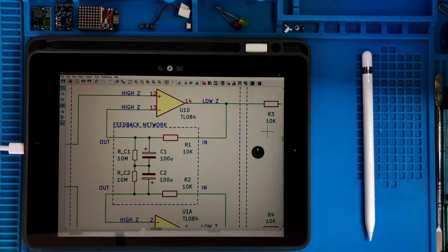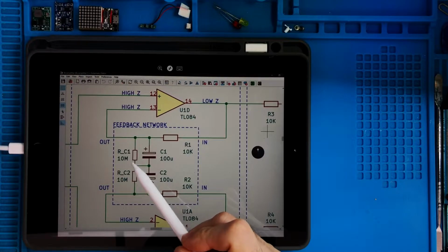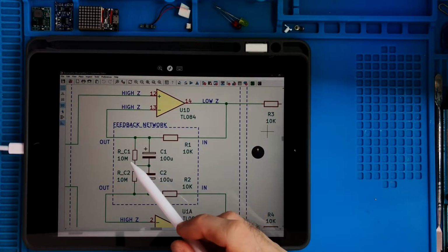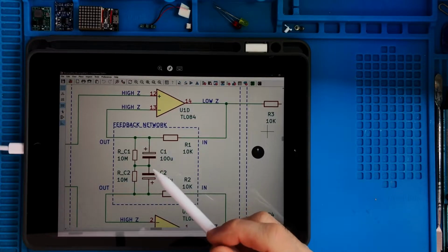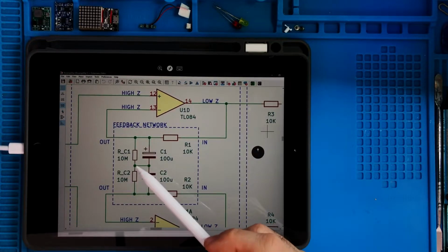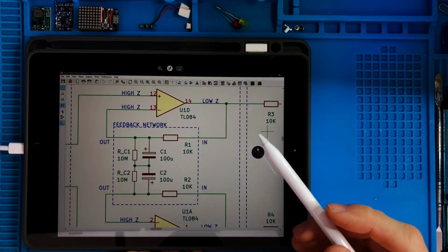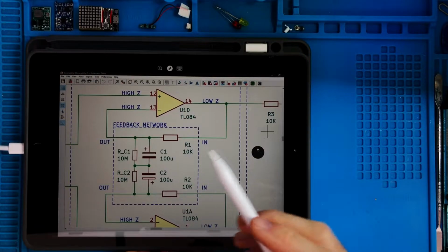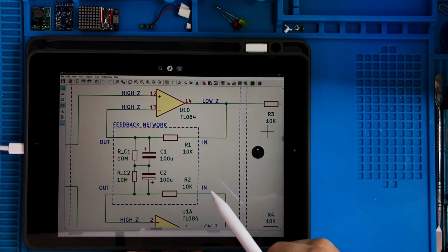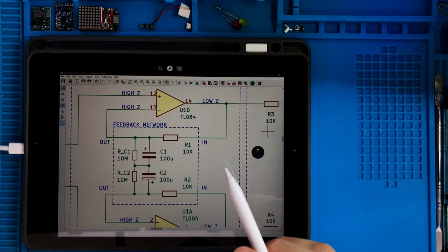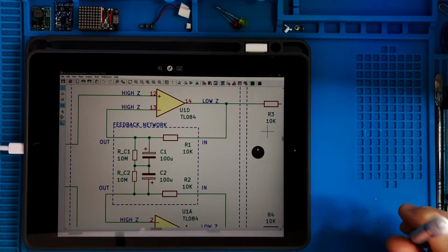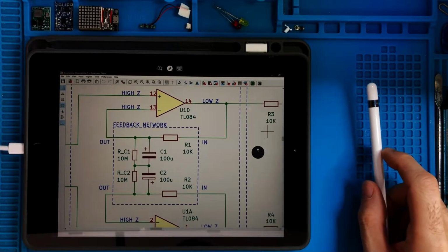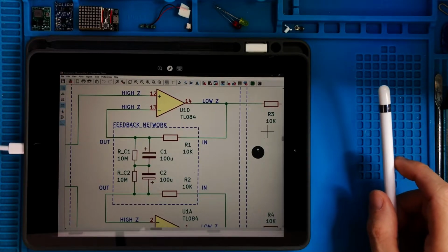So if we go here, this is why we need those two resistors in order to limit the possibility that this transfer function will become infinite for high frequency, or let's say, better saying, we don't want this amplification to become extremely large for large frequencies. This is needed for the simulator, because if we don't put this, when the simulator calculates the simulation, at a certain point it will have to deal with numbers too big for the computer to deal with, and it will throw you an error, something like the divergent calculation for frequency whatever.